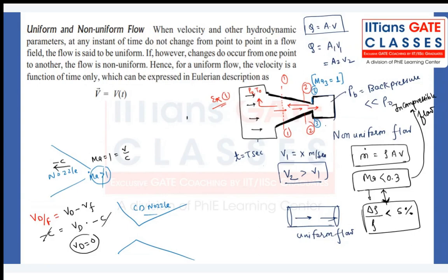So when the velocity of disturbance is 0, the sound waves which tell the reservoir that you please increase the mass flow rate because the back pressure has been reduced, that signal is not being processed to the reservoir. That's why the Mach number cannot be more than 1, right? Those who are very much interested can note down, otherwise maybe the gas dynamics faculty will tell you, right?